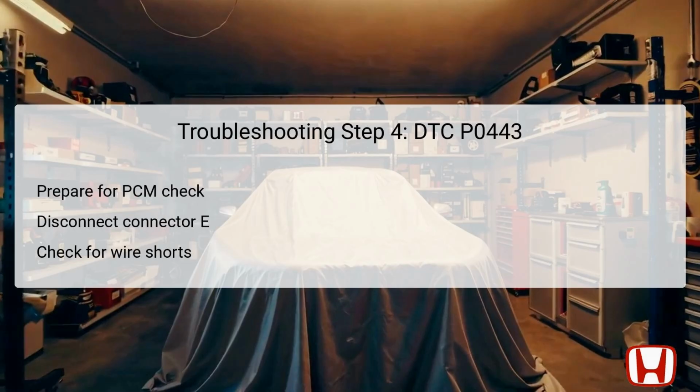In the fourth step of troubleshooting, technicians must prepare to inspect the powertrain control module, PCM. Begin by disconnecting the EVAP canister purge valve connector and then the PCM connector E. This disconnection is crucial for ensuring that each component can be tested in isolation.